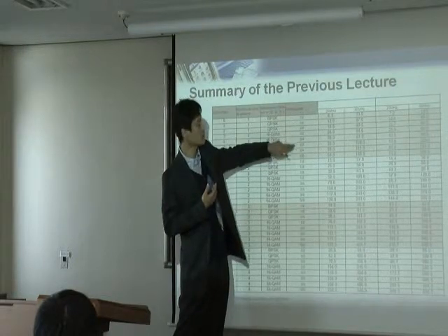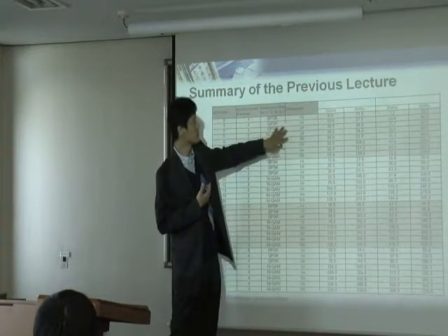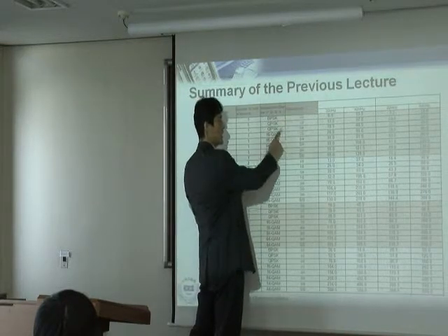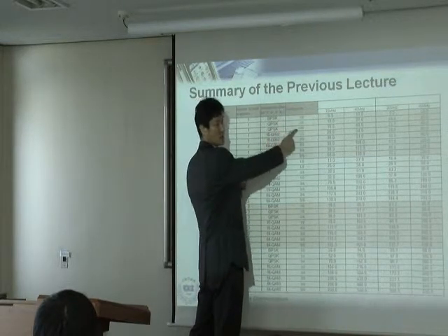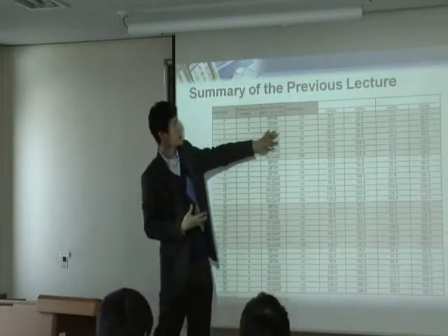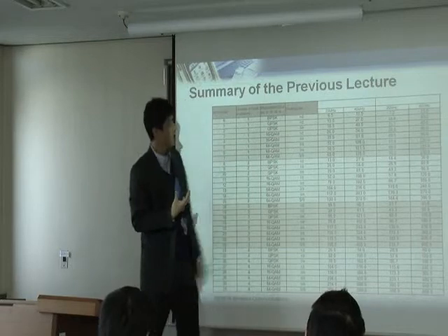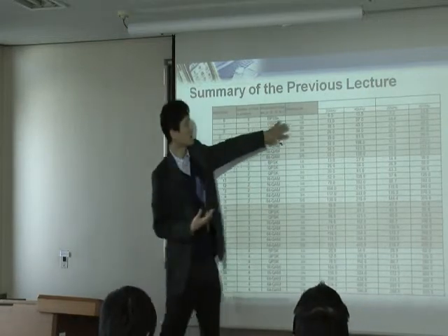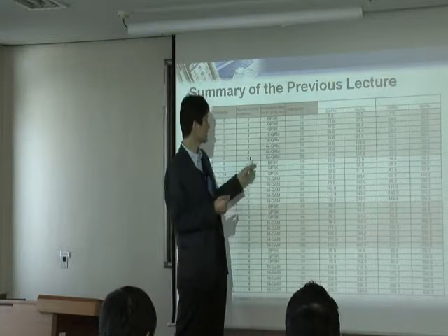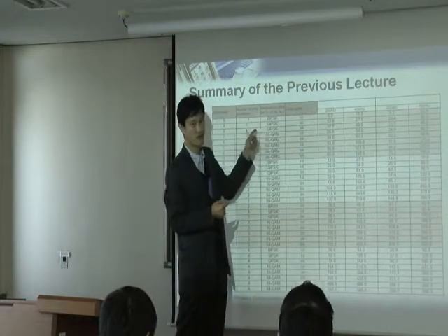These are actually the popular coding rates. So they put them together and make combinations: BPSK with half, QPSK with half, QPSK 3/4, things like that. So it's pretty clear from the modulation and coding rate perspective. When you put this together, you can calculate the spectral efficiency. This table does not show that, but you can calculate it.